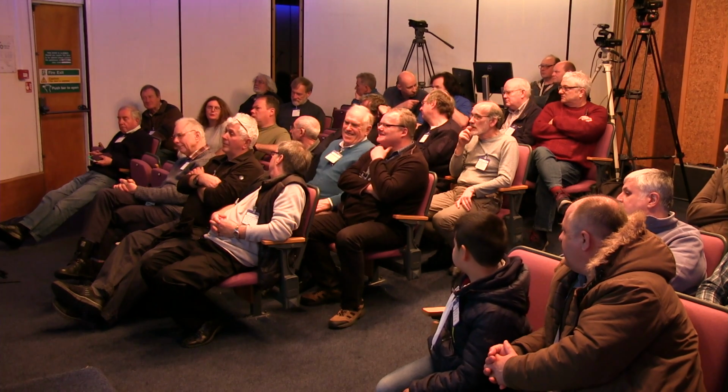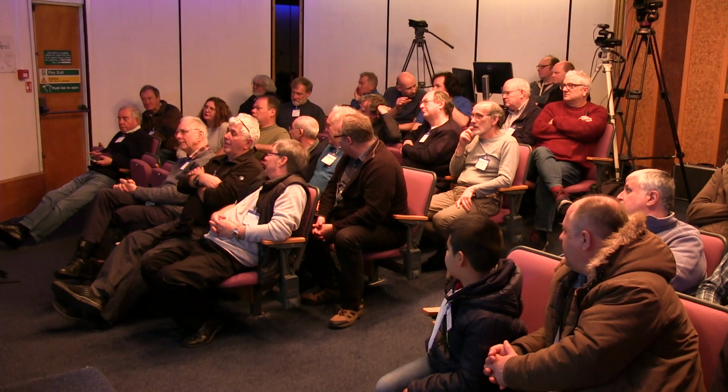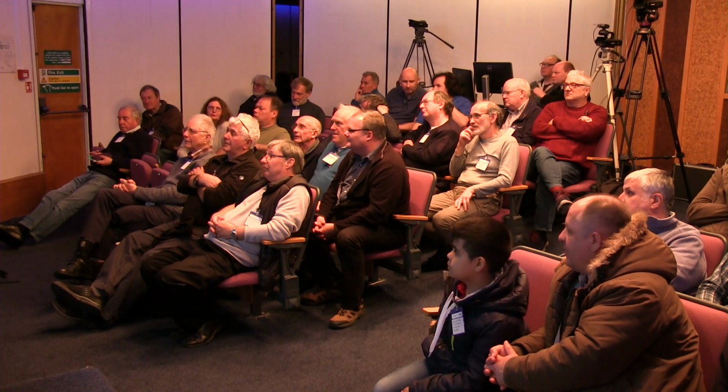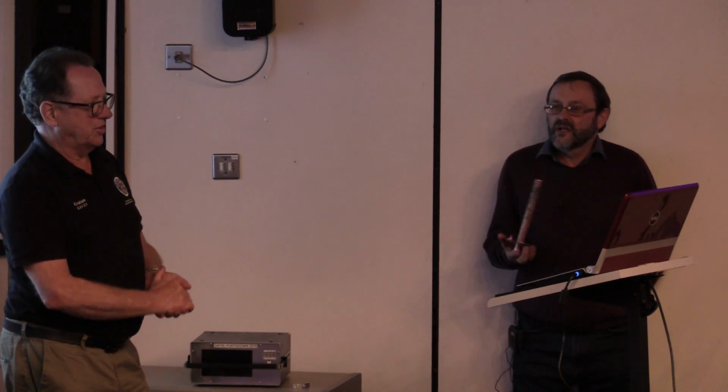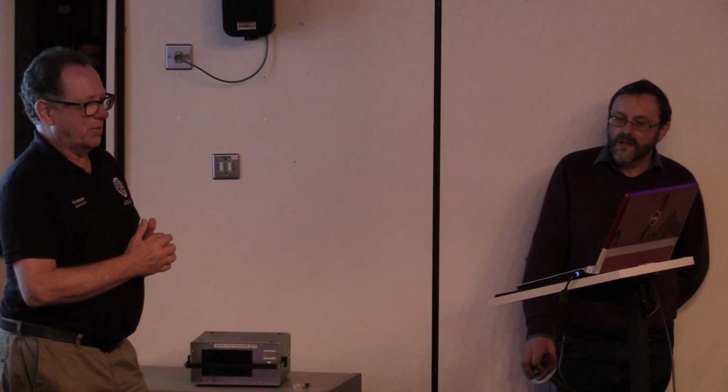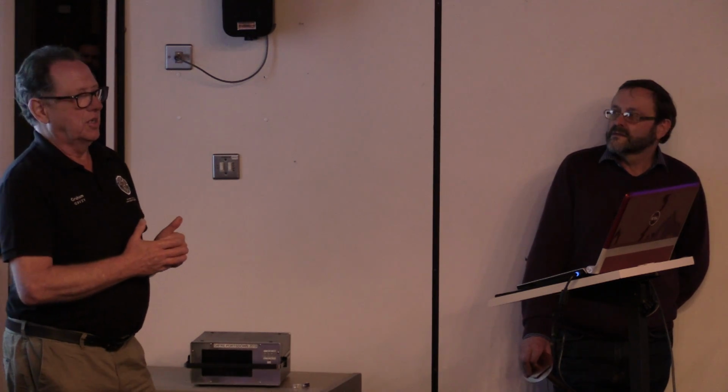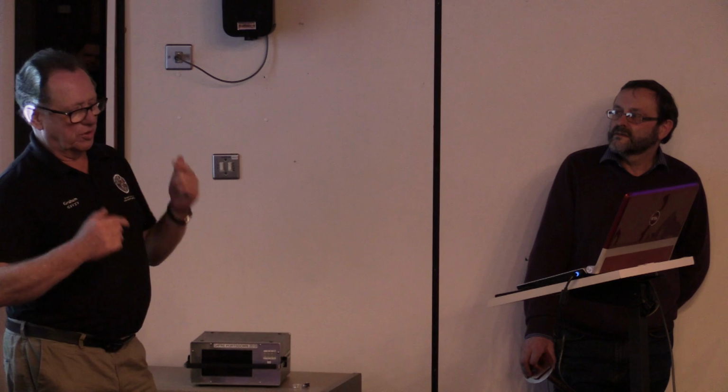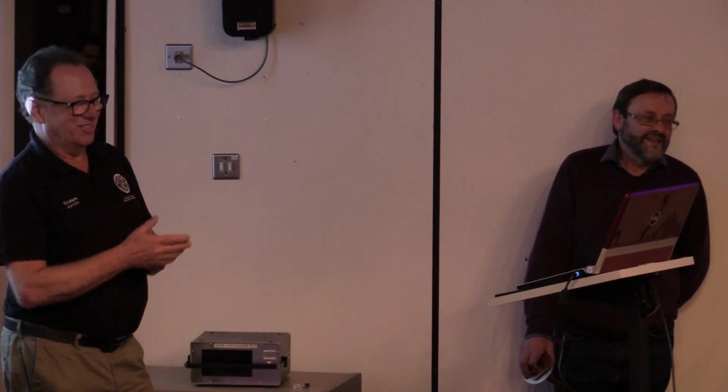It's probably obvious to everyone that you need a bias T in there if you're going to use an SDR for driving the octagon. You'll blow it up if you don't. Yeah, that's a good point. Bias Ts are again readily available on the internet, or you can build them. And JW's done the designs for one. And Noel made a comment that for the wideband transponder you need 18 volts to use the horizontal probe on the LNB. As John has said, or you turn the LNB through 90 degrees and you achieve the same thing.